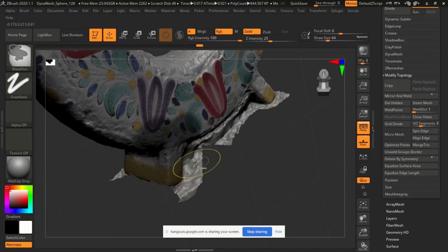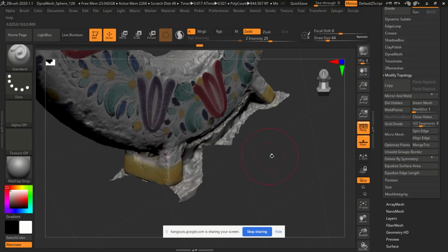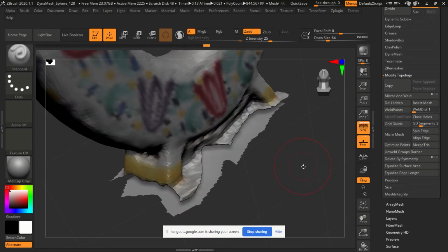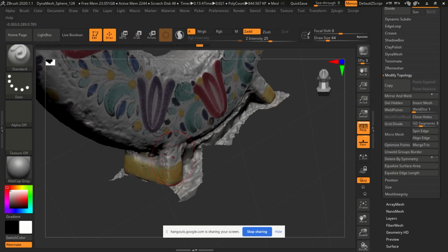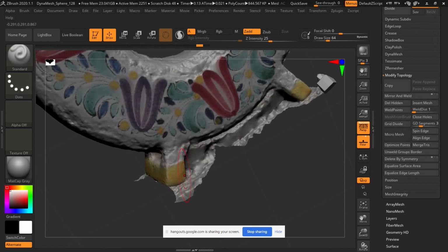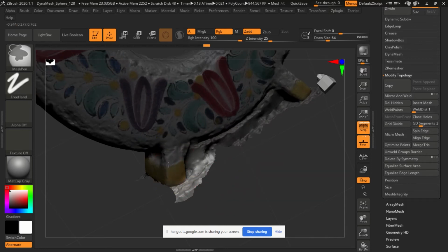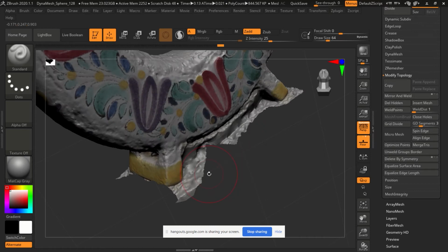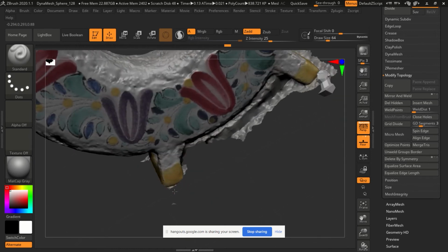If you want to clear your mask, you can hold Control and click drag a box, if there is a masking. So I'm going to mask, I'm going to invert. I got a little bit over, so I'm going to paint it back in. Control W, Control Shift, click on this, and then I can invert and delete hidden.